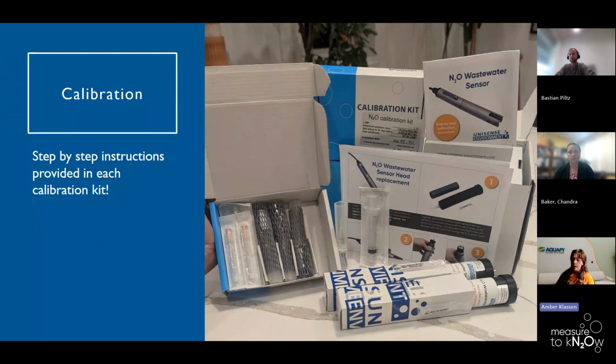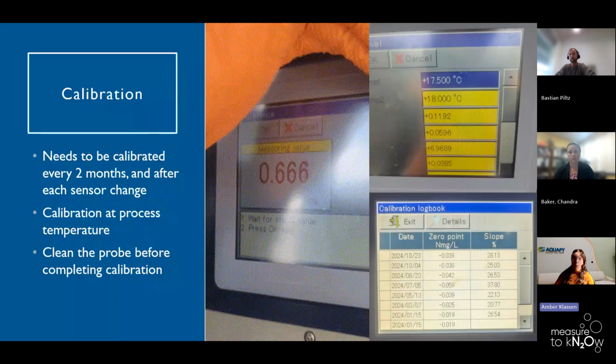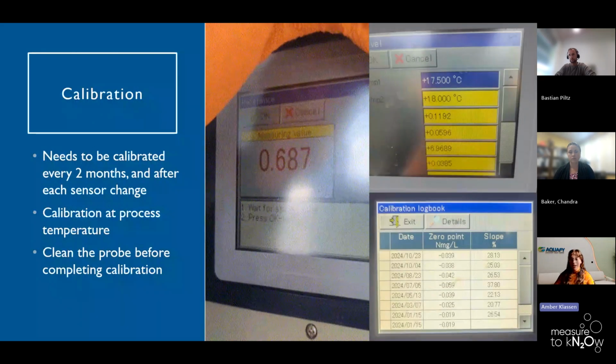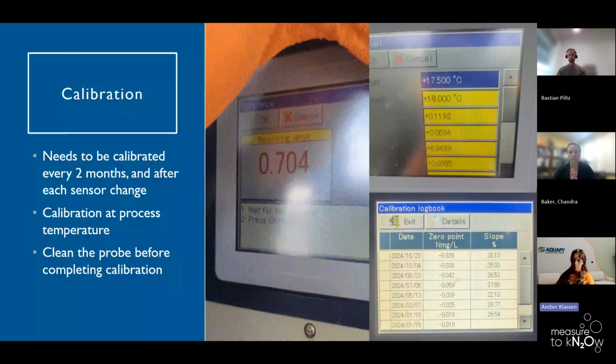The sensor does need to be calibrated every 2 months or plus or minus 3 degrees Celsius of temperature fluctuation, and then also after each sensor replacement. So on the left, the video that you're seeing there is what the HMI screen looks like once the sensor is placed into a calibration solution.